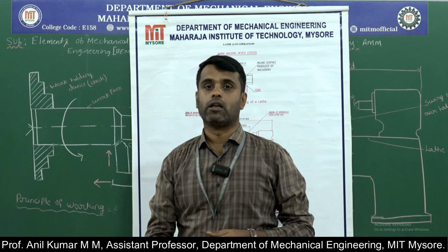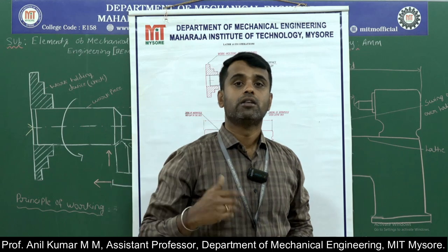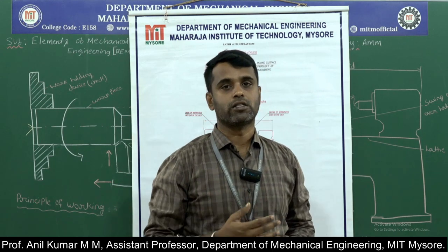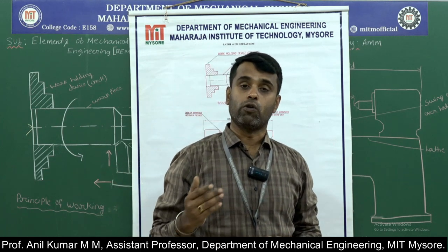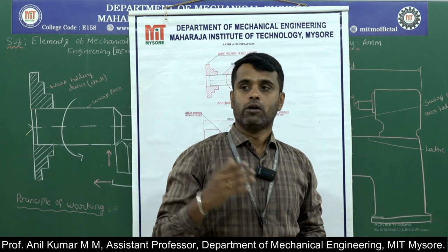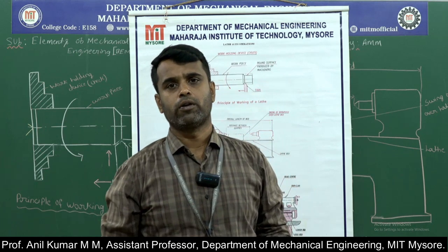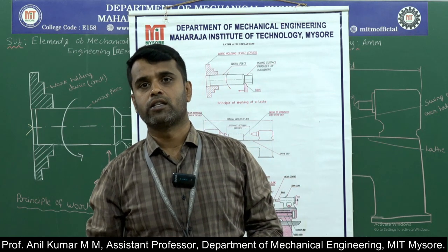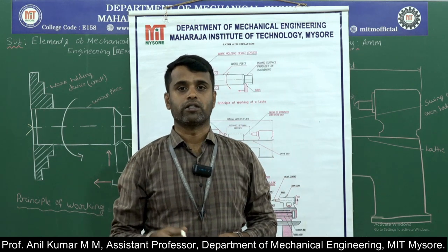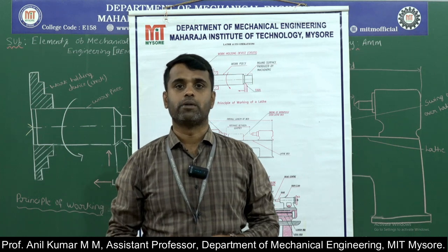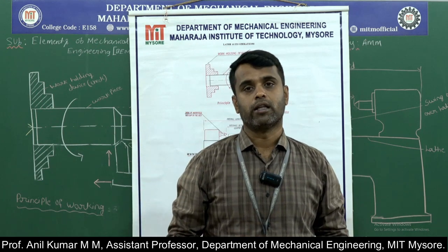Next we discussed the lathe. What is a lathe? A lathe is a machine tool generally employed for producing cylindrical shaped components. It is the mother of all machine tools, a very versatile machine and the oldest type of machine tool. With this lathe we remove the excess material from the workpiece to get the desired shape and size by using a single point cutting tool. There are various types of lathe machines available: engine lathe, speed lathe, capstan lathe, turret lathe, automatic lathe and CNC lathe.